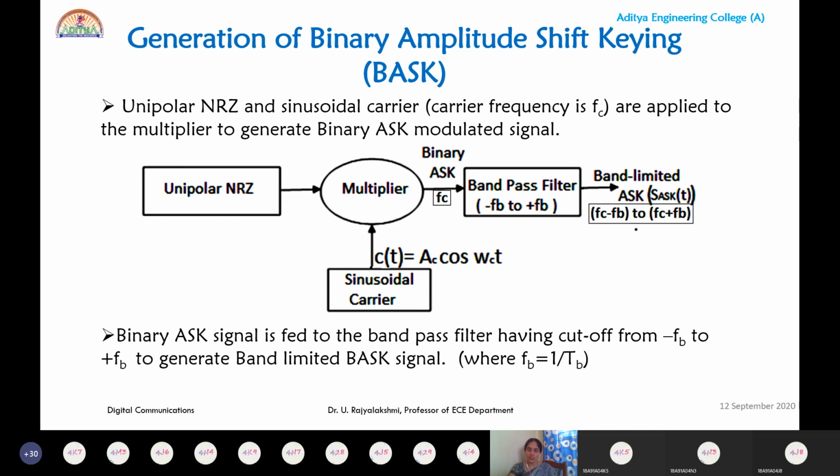What is the magnitude of ASK signal when the input data is 0? 0, ma'am. Yes, there is no magnitude at all. Okay, thank you, ma'am. And wait, one more thing. What is the Euclidean distance for ASK signal? Whole root Ps into Ts.